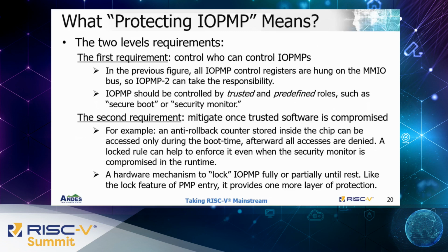As to the answer of who, it is supposed to be a trusted software such as a secure boot or security monitor, and it's usually predefined. As to the second requirement, we want to provide a mechanism to enforce some important rules unchangeable, even when the trusted software is compromised. It's similar to the per-entry lock of PMP. Lock means before reset, the locked content is not changeable.